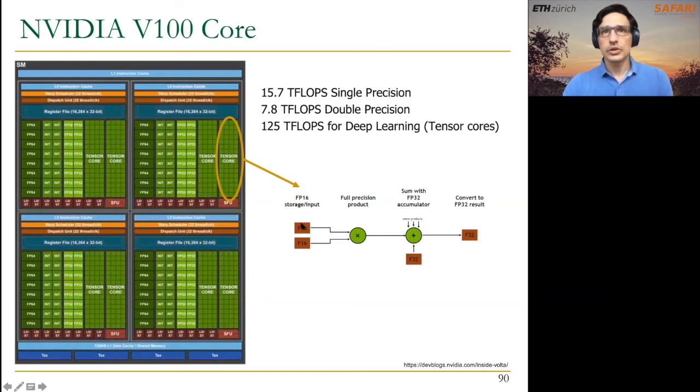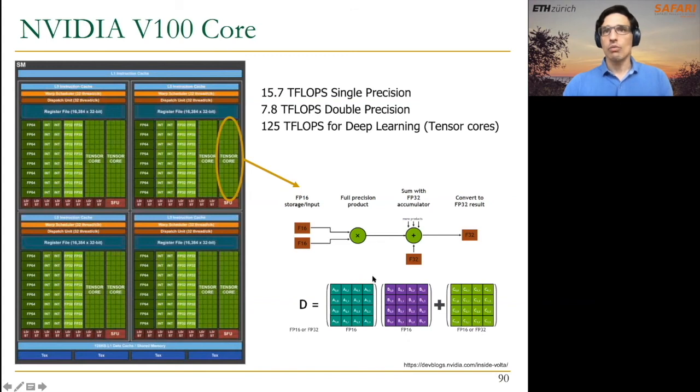What they essentially do is take 2 operands represented in floating point 16 bits, perform a multiplication, and then accumulate with some value coming from the accumulator, and store the result again in the accumulator. So using these tensor cores, we can divide the whole matrix multiplication into small tiles, and each of these tiles is assigned to different tensor cores, and this way we can do the matrix multiplication much faster.